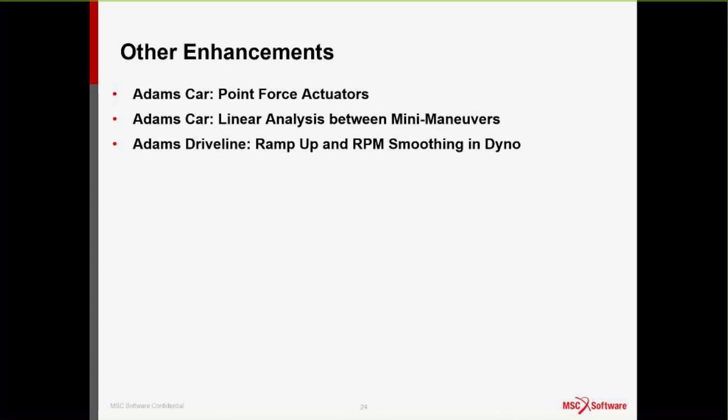So what we've done here to resolve these problems is that the AC dyno UDE has been enhanced to account for that cyclic irregularity originating from the engine stroke. Specifically, there's a smooth torque fade-in over time using a step function to optionally eliminate initial transients. And a new state variable has been employed to track the mean RPM value, the mean angular velocity, so that the engine torque used is based on this mean RPM rather than the oscillatory actual RPM that was used previously.